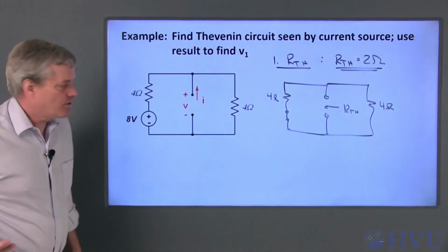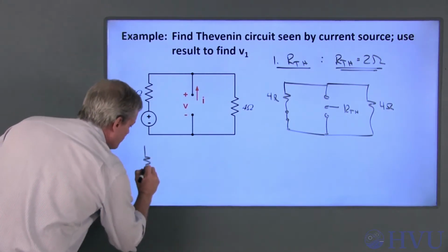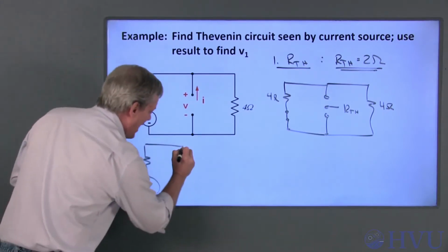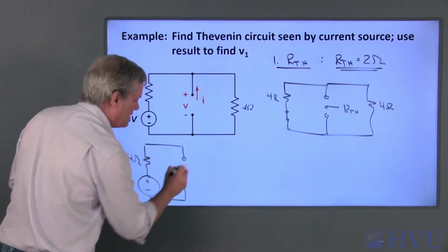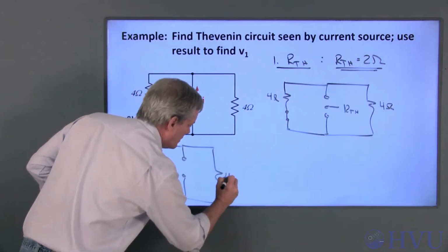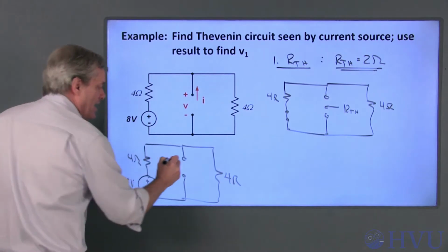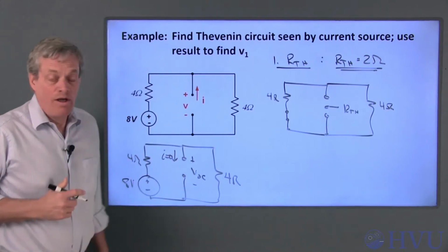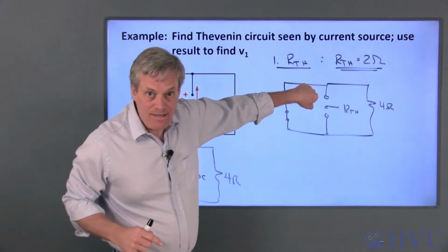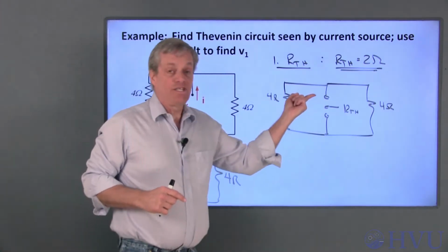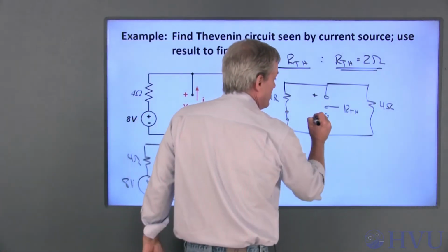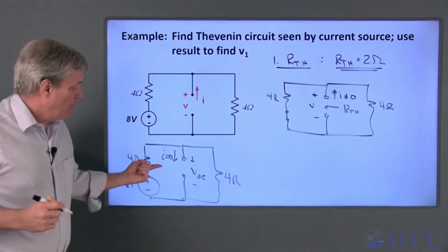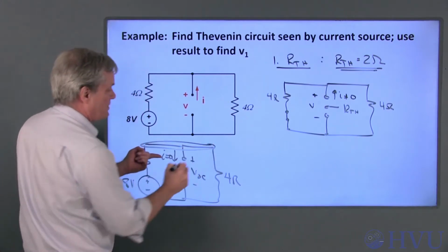Now I'll calculate the open circuit voltage. I replace my voltage source, so I get my sources in circuit A back. These are the terminals I'm interested in. Now it's important to keep in mind that this is an open circuit voltage, so this current is equal to 0. These terminals look kind of like these terminals. But in these terminals, it's not an open circuit. We're finding a relationship between voltage and current, so we don't assume that the current is 0. In this case, current is 0.